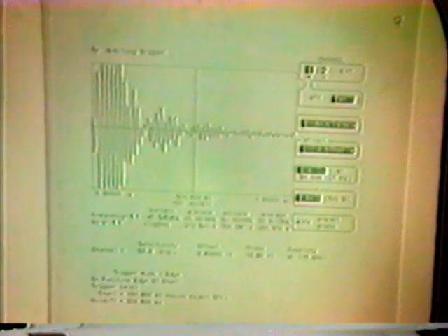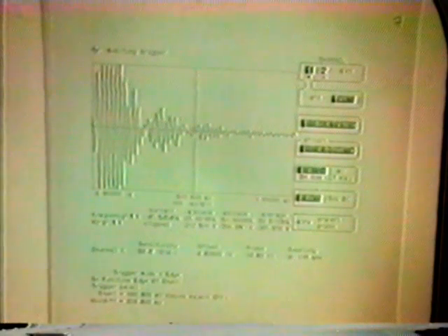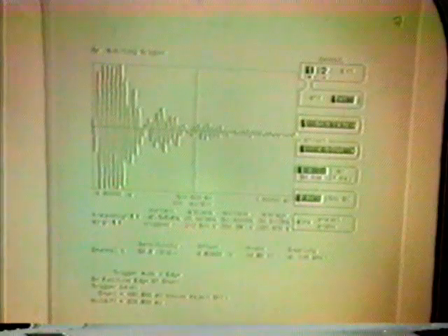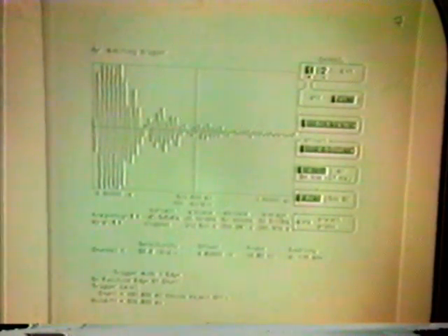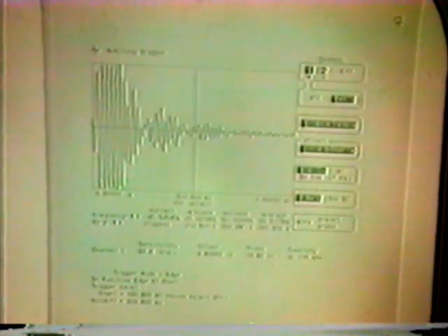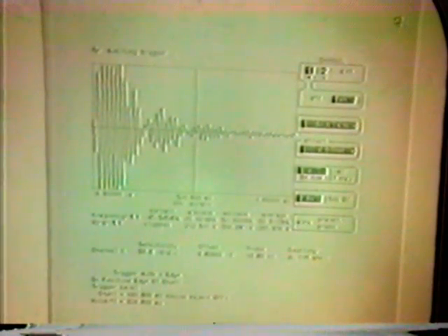Here again the same thing. And now the time base is much higher than the ringing frequency. So in principle we see that there are oscillations, and these oscillations don't change when we make the capacitor banks higher by a factor of 1,000, or change the coil. The ringing frequency does change, but these, which sometimes people call parasitic oscillations, don't change. They persist the way they do.